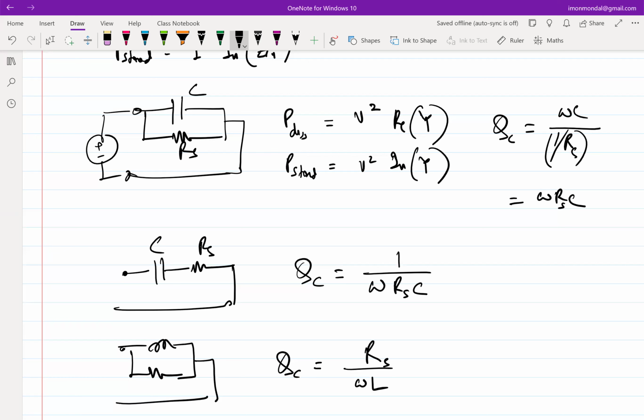You just club everything into Q and say, what is the Q factor of your element? For example, often you will hear that the Q of your inductor at 1 gigahertz is approximately 10 or 15, which essentially means that omega L over R is equal to 10 or 15 at 1 gig. If you know that information, you automatically know that at 2 gig, it's probably 20 or 30, right? Or at 10 gig, it's probably like 10 times of that, 200 or something like that, right?